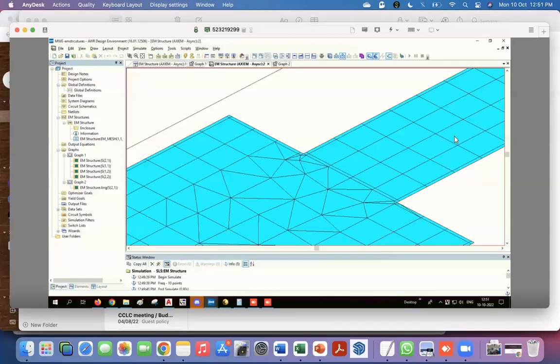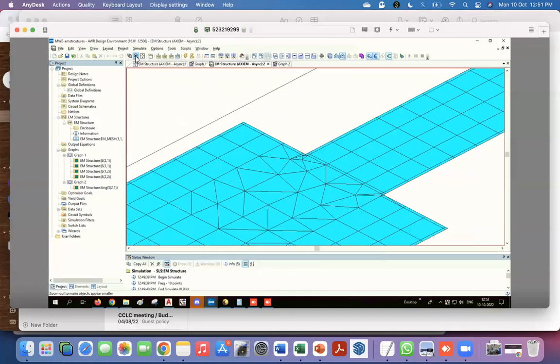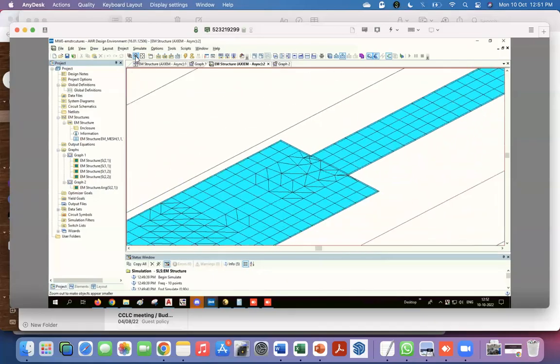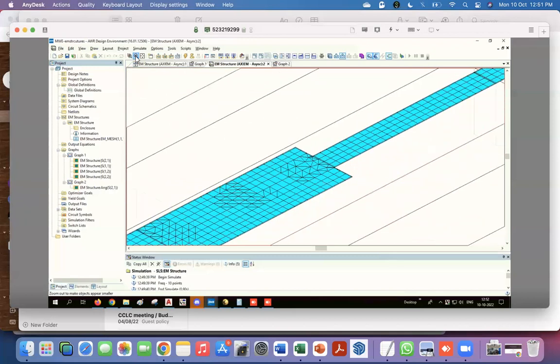And it understands the dimensions, that here it's shorter and there it's longer. So it only looks at the edges. So sometimes staring at the mesh might help: if your results are weird, you can look at the mesh and say, okay, maybe this is why, let me try something differently.